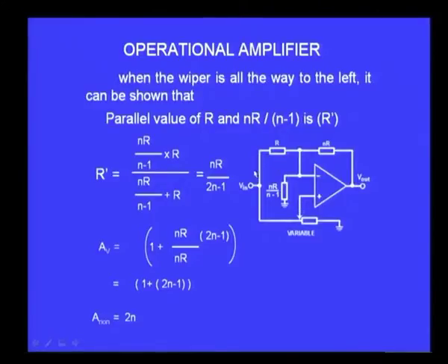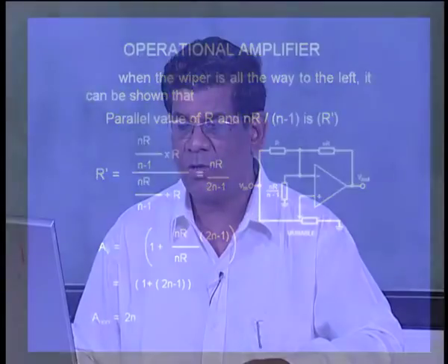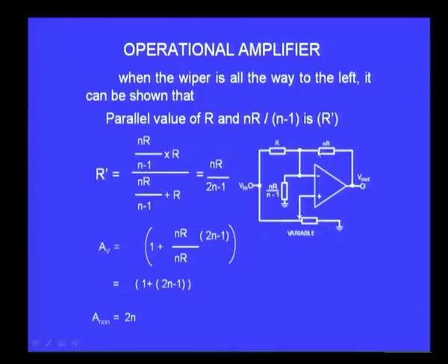At that time, I should ground the inverting input terminal and then calculate the gain. After that, I should ground the non-inverting terminal and assume only these resistors are present and the input is driving only the inverting terminal, and find out the gain, and I should add the 2 by the superposition theorem to get the overall gain of the amplifier.